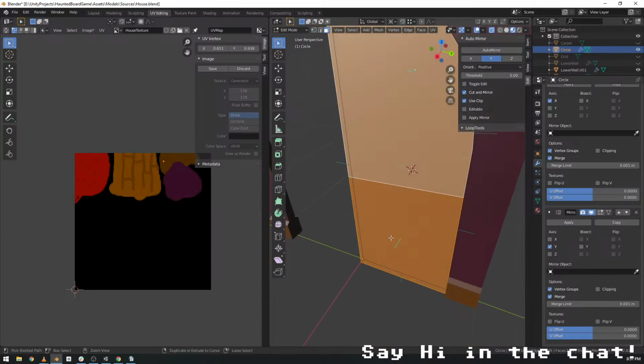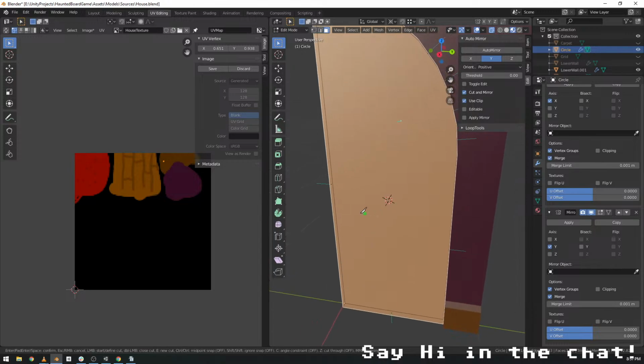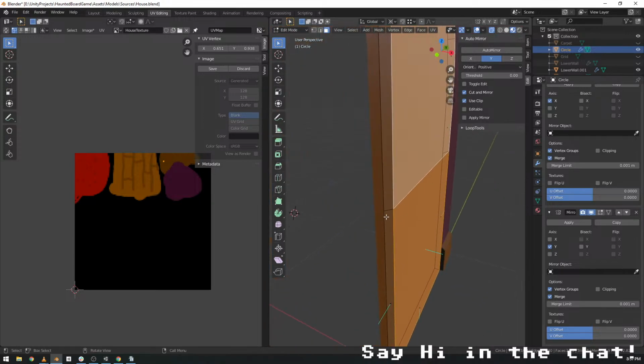And I didn't do cut through. Okay, so the knife tool is just what it sounds like. You cut with a knife, but you can cut all the way through. Like right now, it's only going to cut this front surface instead of these edges. But I can hit Z, and not Windows key, and turn cut through on. Click, enter, and now it cut all the way through.